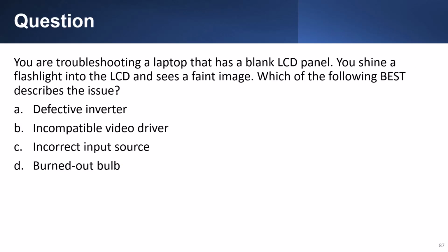Question: you're troubleshooting a laptop that has a blank LCD panel. You shine a flashlight into the LCD and see a faint image. Which of the following best describes the issue? Answer: defective inverter.